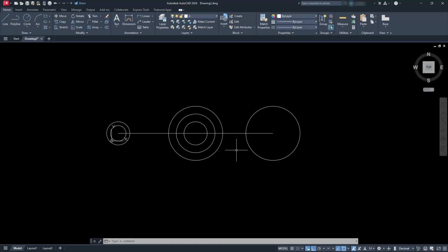Now I have to place 2 diameter circles on the inside of this. So I'll go to circle, center, diameter. Let's place this one at this endpoint here. Give yourself a preview of it. Type in 60. Come back to circle, center, diameter. Go right to this endpoint. Again, stretch it out. And this one will have a diameter of 40.